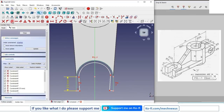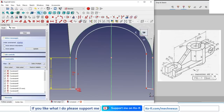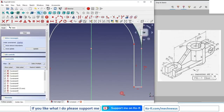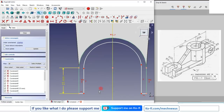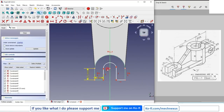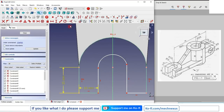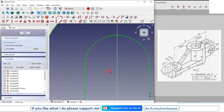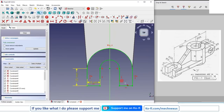Apply the respective constraints. So this is vertical, and these two horizontal. This is already horizontal. Okay. Now I will apply the thickness, which is 10 mm. Here a tangency is required, so I will select on tangent and apply the tangency. Okay, so this is our profile.